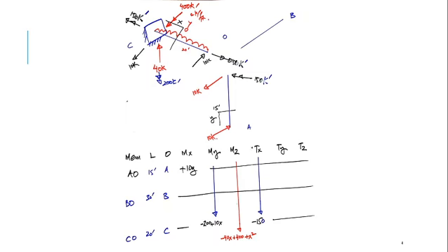The sectioning is very easy and a very important point of this flexibility method you had been doing in your BSc. Because this member has no loading, one section would be enough. You know that this is C. So I have taken this section BO. It's always good to take the origin at supports. Again, if I consider this section, you will notice that the applied load is here, so I think this section would be enough.